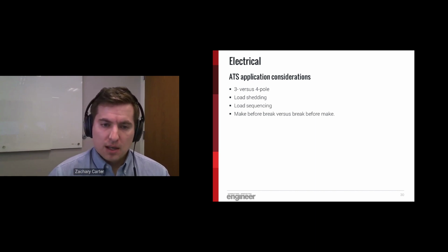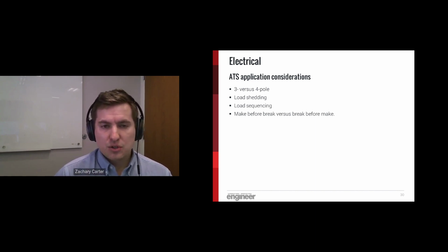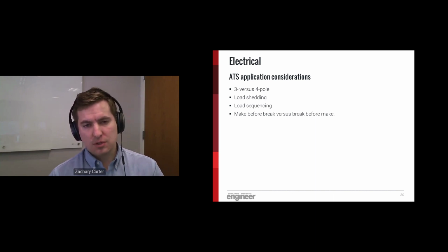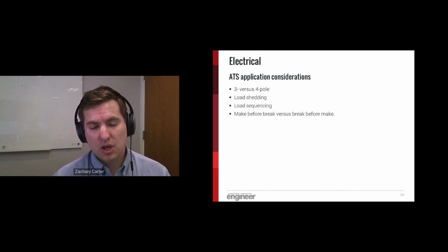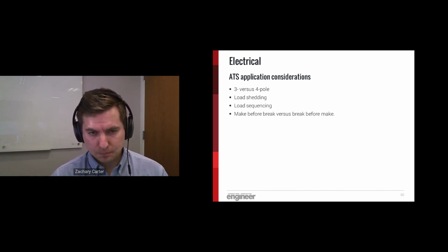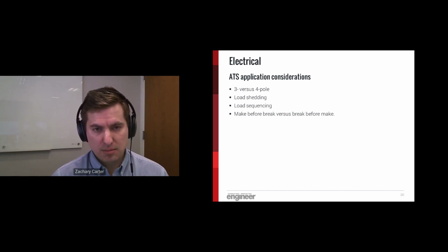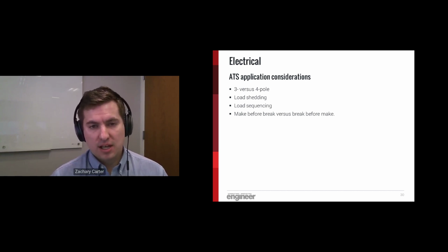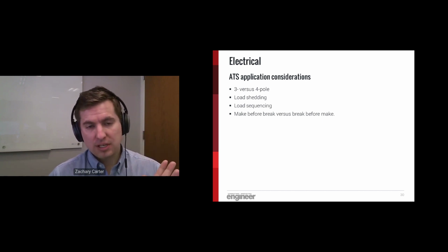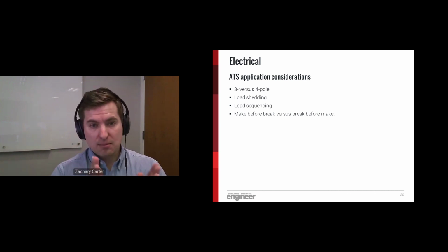transfer switches. And then another consideration too is the make before break or break before make transfer switches. Some folks on the call might know these as closed transition or open transition transfer switches. Closed transition is the make before break. We see this a lot in the healthcare facilities where they're making both the utility connection and the generator connection to the load terminals for a very small amount of time. We're paralleling those two sources. So we're making before we're breaking into the other source. So it's a closed transition.